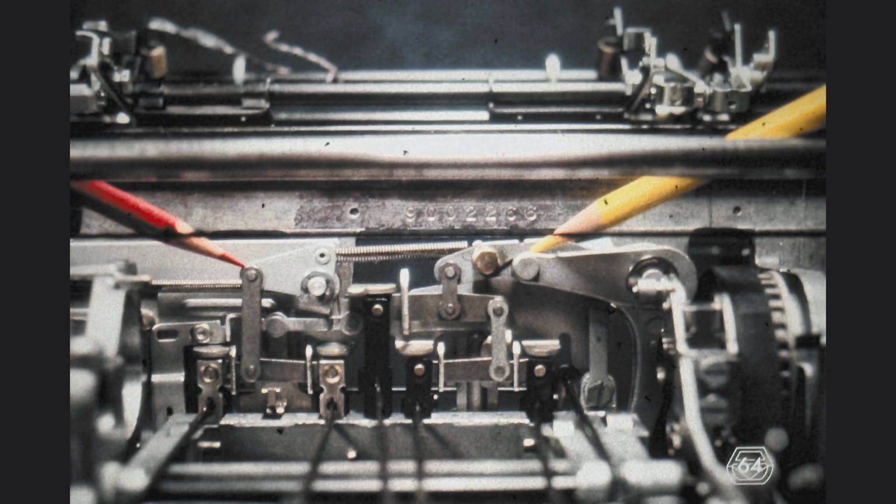The red pencil indicates the connection between the tilt tape mechanism and the tilt differential. The vertical link of the tilt differential, below the red pencil, is attached to the tilt bell crank. When the link is pulled down, it has the ability to turn the tilt bell crank counterclockwise, transmitting the motion from the tilt differential to the tilt tape mechanism. Notice that the tilt differential has two selector latches.